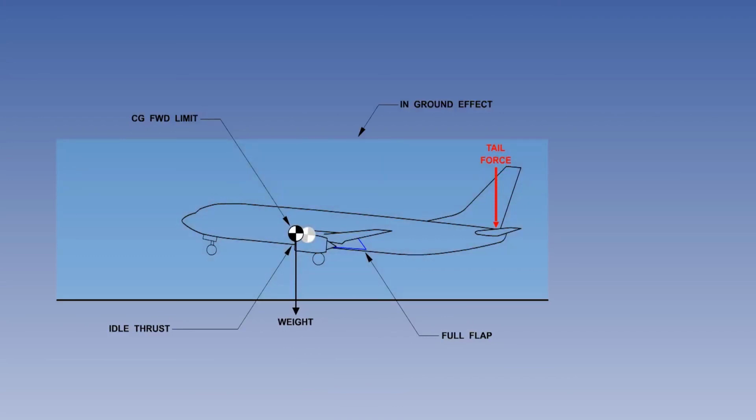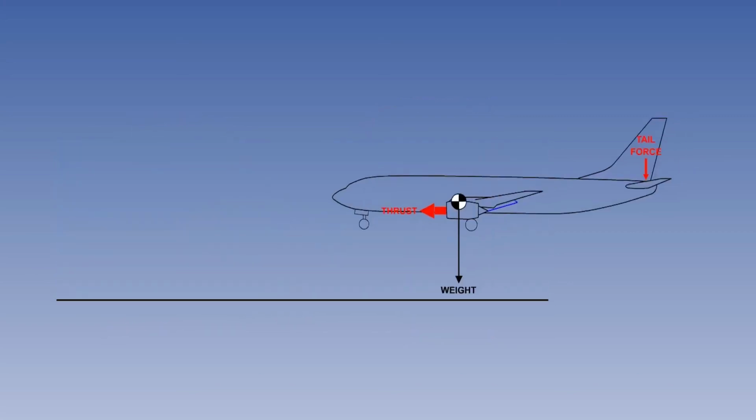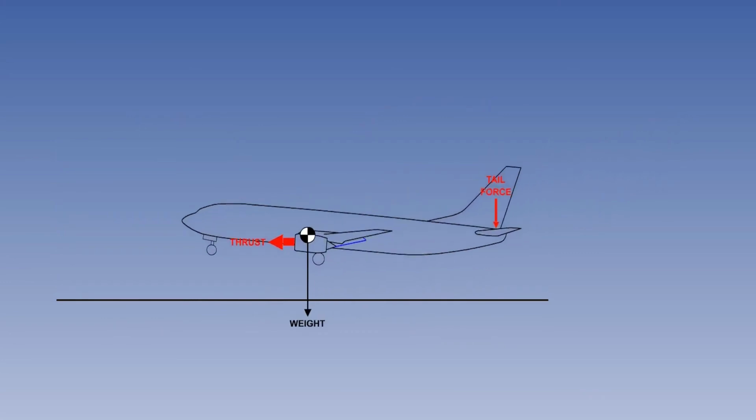Each of the longitudinal control power requirements are critical for high longitudinal static stability. If the forward CG limit were accidentally exceeded, the aeroplane may encounter insufficient controllability in any of these conditions. To conclude our study of longitudinal static stability, it must be remembered that the forward CG limit is set by the minimum permissible controllability, and the aft CG limit is set by the minimum permissible stability.